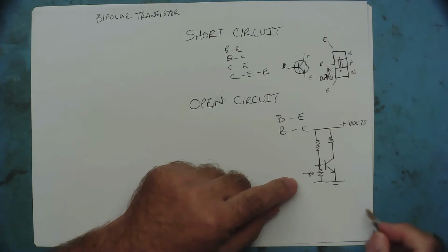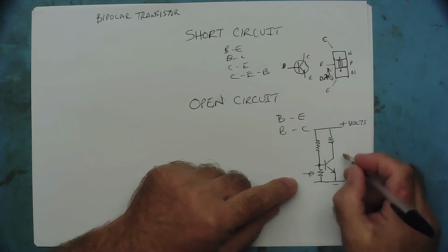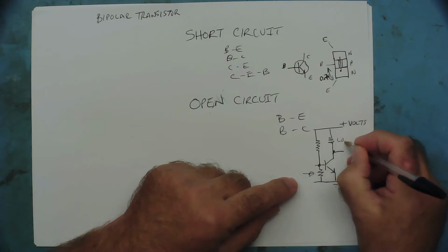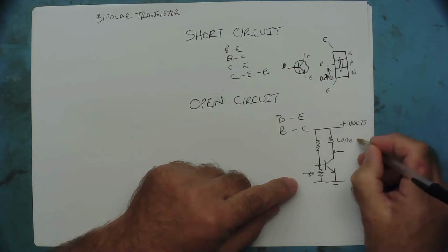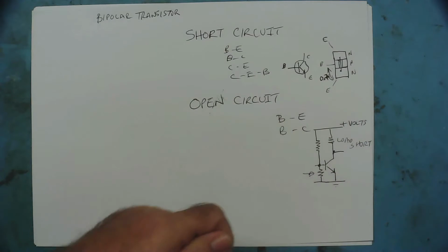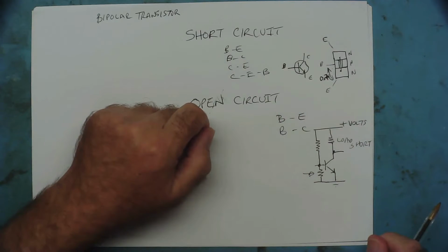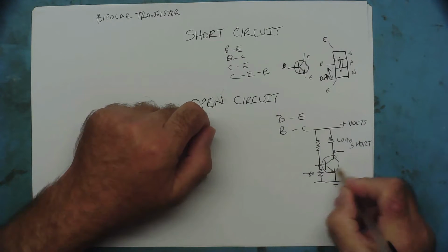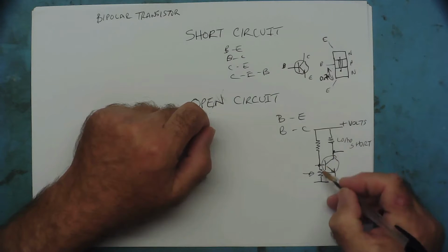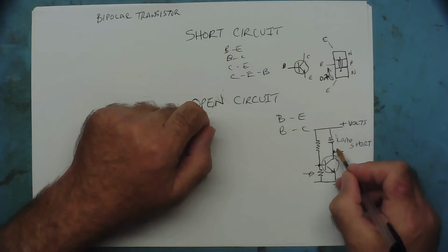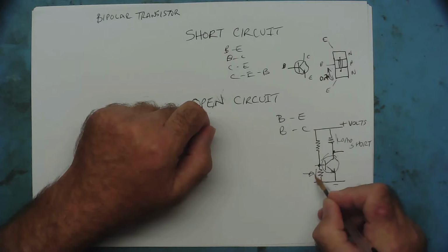Yeah, that's fairly obvious. Now, what you can have is an interesting situation with this. Imagine this is feeding some sort of load. So this is your load, and the load goes short. It's driving a speaker and somebody accidentally connects the wires together and short circuits the speaker. So this transistor goes bang, and goes short circuit, or it goes short circuit from the collector to the base. If it goes short circuit from the collector to the base, all the current flowing through the load, which is short, flowing through here, which is short, is going to flow through this resistor.